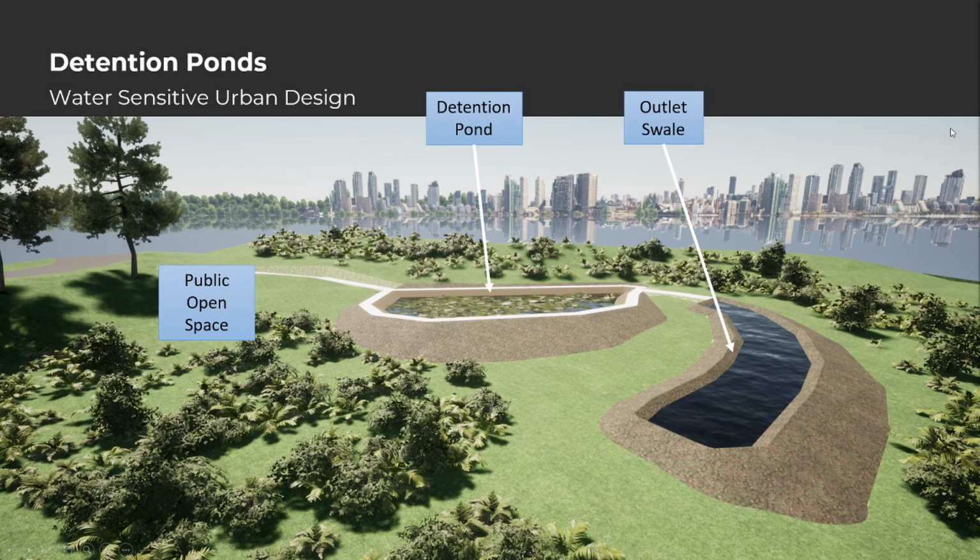So, let's talk a little bit about detention ponds. Now, the concept in traditional urban design was always focused on taking stormwater runoff and pushing it into streams as quickly as possible. The problem with this is that it causes issues, and some people call these issues urban stream syndrome. It's mainly that there's increased concentrations of pollutants and solids in the waterways, and also the peak flows cause issues with the waterways. So the general shape of the streams gets damaged and everything else. So there's been a big push on improving water-sensitive urban design. It's also called low-impact design or green infrastructure, or I think in the UK it's called sustainable drainage systems.